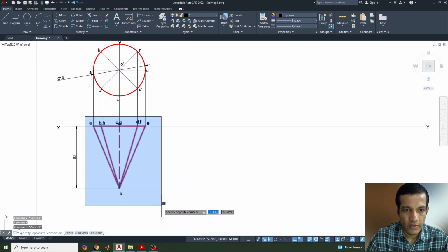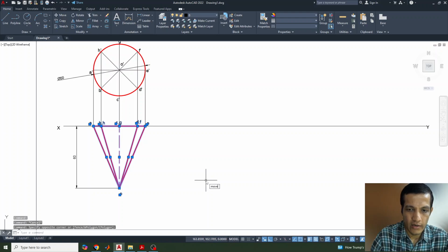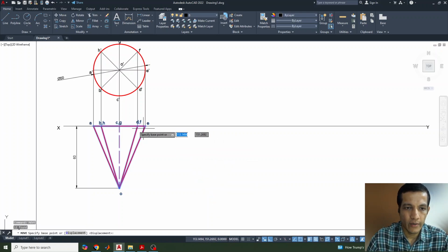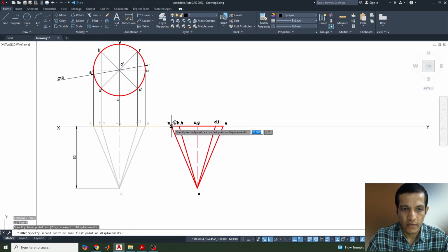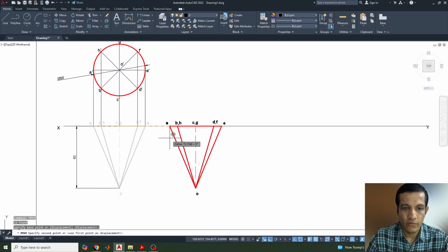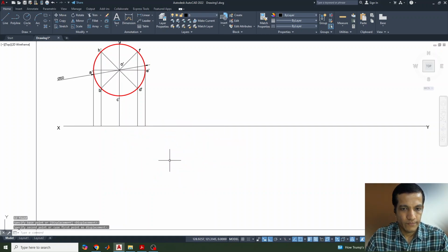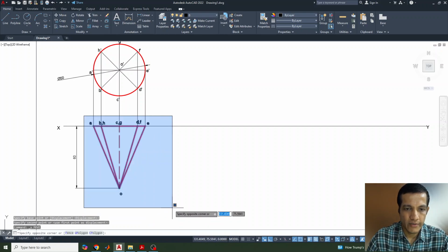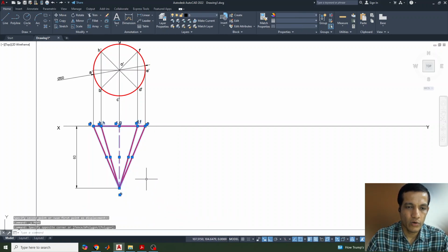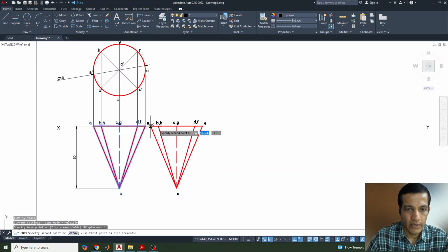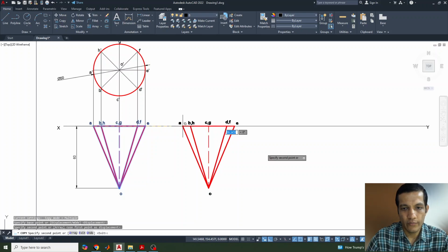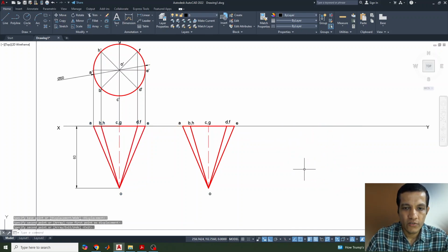Now this needs to be selected and type the move command. By the move command we can move the triangle from one place to another place here. Okay, actually if you use the move command, everything is moving. So what we'll do is copy it instead of moving. If you want to move also we can move it, but copy and move. Otherwise you do one thing: copy, enter, specify the base point here and just move it up to here. Okay, so that is a good way.